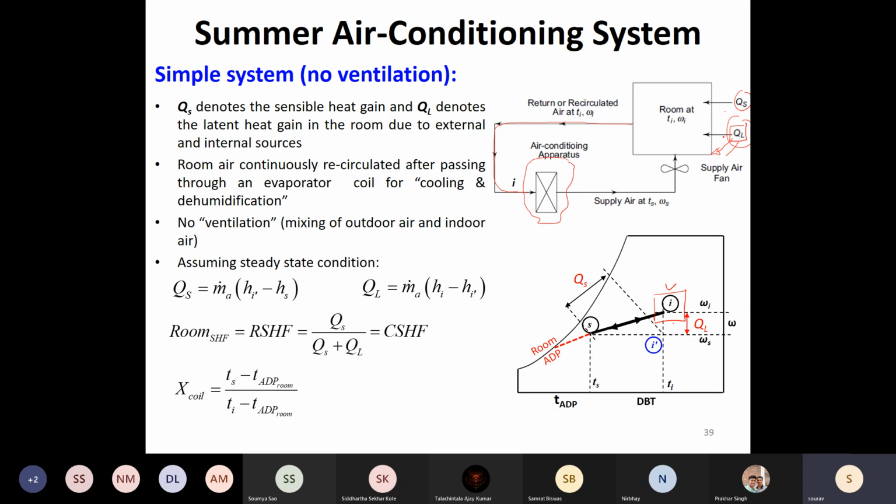Especially in the older homes, there could be ventilations which were provided, and even if we seal them or try to seal them, there will be leakages. So that also brings in both QS and QL. In fact, human activities also lead to some amount of QS. We'll see some general trends and numbers, how human activities can lead to sensible as well as latent load.